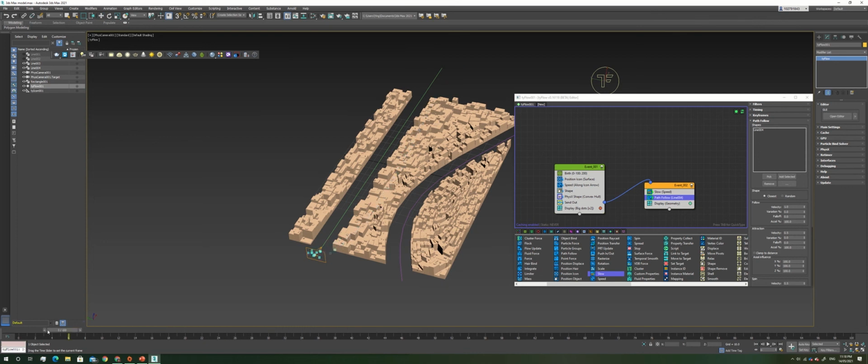When we drag our timeline, we can see that our particles follow our chosen straight line. However, we can see that it doesn't quite follow it perfectly. To fix this in path follow, we can turn off the spin velocity by setting it to 0 and increasing the attraction velocity to 1 and follow velocity to 2.